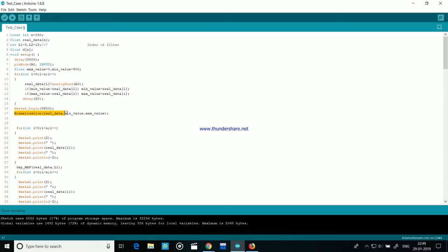This is my normalization function. In this function I have taken the data collected from the pulse to mean 0 and I have divided by the maximum value to get data from -1 to 1, so that all the samples are in the range -1 to 1.